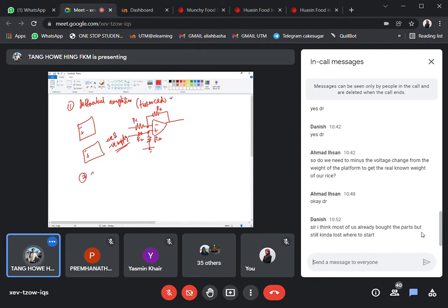And the second step, again, is the differential amplifier, but this round, you try the hard way. It means that you plug it into the breadboard, and then you do the connections. Because for the hard way, I'm not sure what kind of op-amp you are using. You may use the TL074 or TL072, or even the most classic, most probably the 741. I think it's UA741. It depends on the factory.